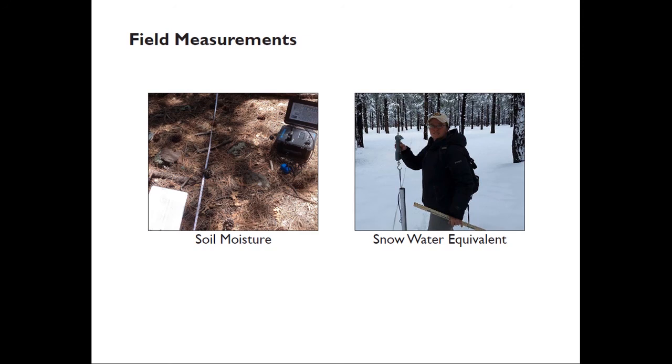3 weeks. And what depth are you measuring soil moisture? So these probes are over the top 30 centimeters of soil, and then the continuously recording probes we had going down to 50 centimeters, which is where you start hitting rocks there. Most of the analysis of rooting depth on ponderosa says they go down to about 50 centimeters.